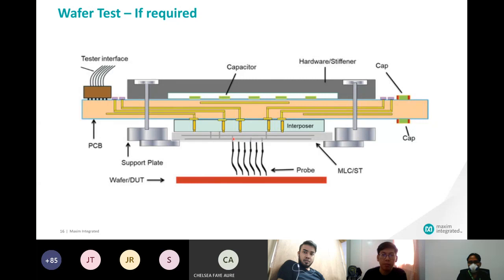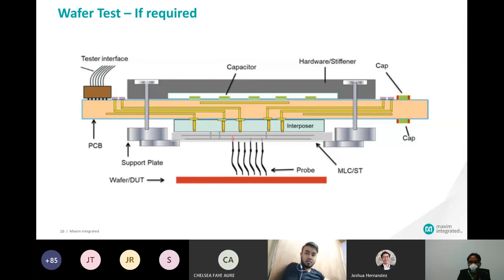So if you work with those vendors, what you'll get are singulated dies. They won't give you the whole wafer because it contains die or products or designs from someone else as well. So what they'll give you are the singulated dies, teeny-weeny die. And you'll have to figure out how to connect that die to an external circuit, which is doable if you have a probe station, which unfortunately I haven't shown here.